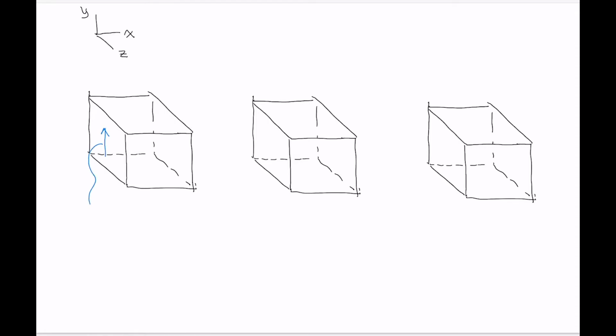Okay. Now, if we name this shear stress, instead of shear stresses getting named with one subscript, we actually need to name them with 2 subscripts to define them. So the first subscript tells you which axis the plane that the shear stress is acting on is perpendicular to.